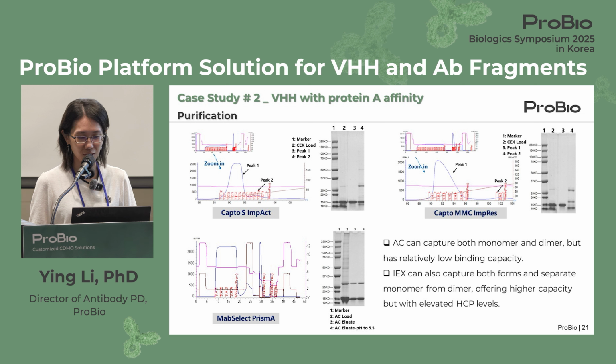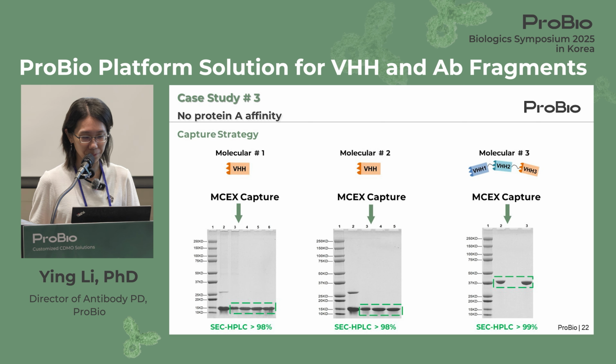Typically, either using CEX resin or mixed mode CEX, we can have good resolution between the monomers and dimers, and offer high binding capacity compared with affinity resin. However, if we utilize the mixed mode CEX or CEX as a capture step, we would typically expect higher HCP levels that need to be further reduced, typically through 3-step chromatography.